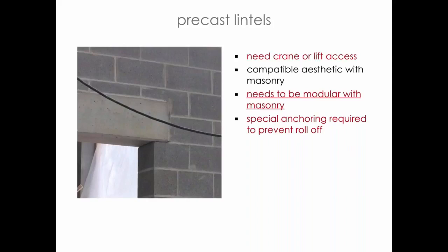Special anchoring, you want to make sure that as you set this, as it gets deeper, even more anchoring that you have to consider to make sure that you don't have any roll-off in the design. So there's some things that we have to think about. You have coordination. You have to order the precast element. Masonry, we talked about this in a lot of seminars. Scheduling-wise, masonry is typically on some pallet someplace ready to get built the next day. Yes, there's steps in there, but it's ready to use right away. So scheduling-wise, precast, we have to think about that just a little bit more.